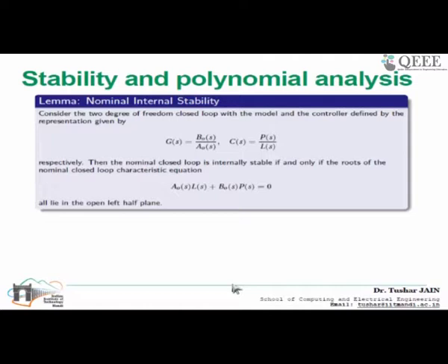First we show that if all the poles have a negative real part, then the system is asymptotically stable. If you recall from the very first s plane I drew, there were the real axis and the imaginary axis, and I was saying that even if it is a complex root or a real root, I am concerned only with the real parts.